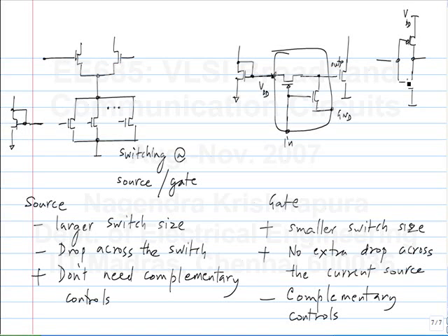So in this case, it means that the VGS of this device has to be greater than the threshold voltage of the PMOS transistor. Bulk to the source of the PMOS. You mean to optimize it, you want to connect it here. Okay, that's fine. You don't want to further deteriorate the threshold voltage of the transistor, so you don't connect it to VDD. That's what you're saying.